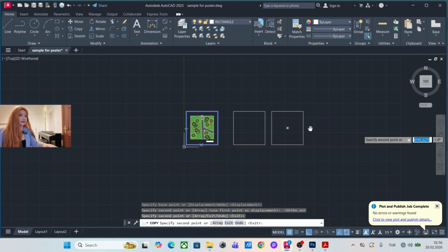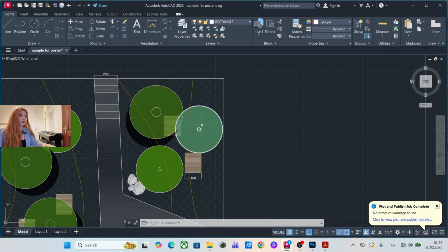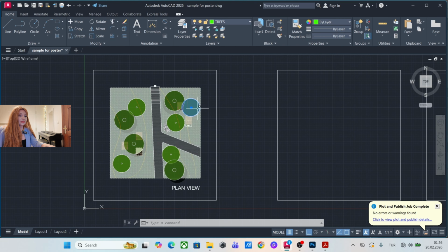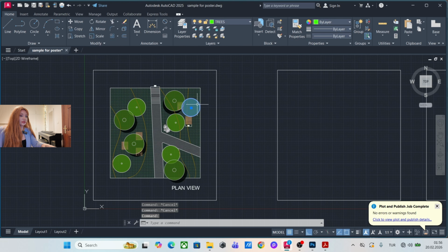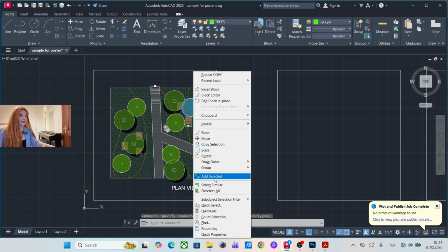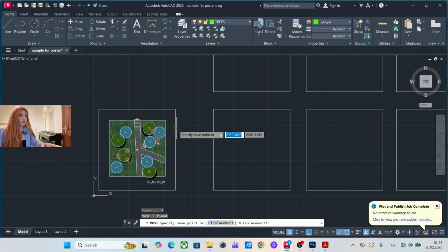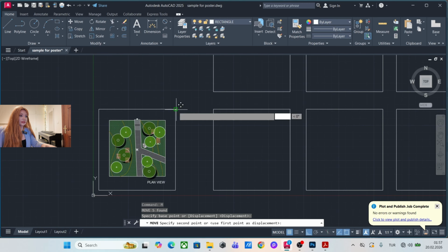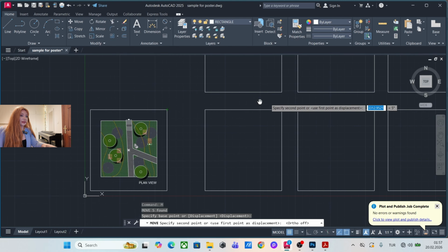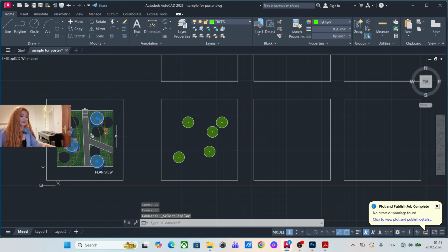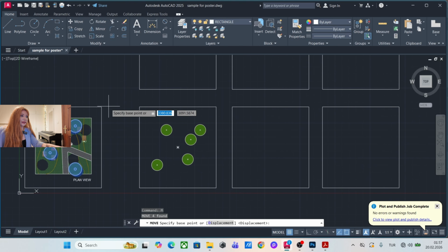And then copy it. And then I dissect my plan layer by layer. I can use layer isolation by writing LAISO or clicking on this isolate, but I sometimes do it like this. I choose the object and say select similar, and then choose my trees. I press M for move. I press on the corner that I want to pick my objects and then paste by using the same corner. Click, right click, select similar, M.